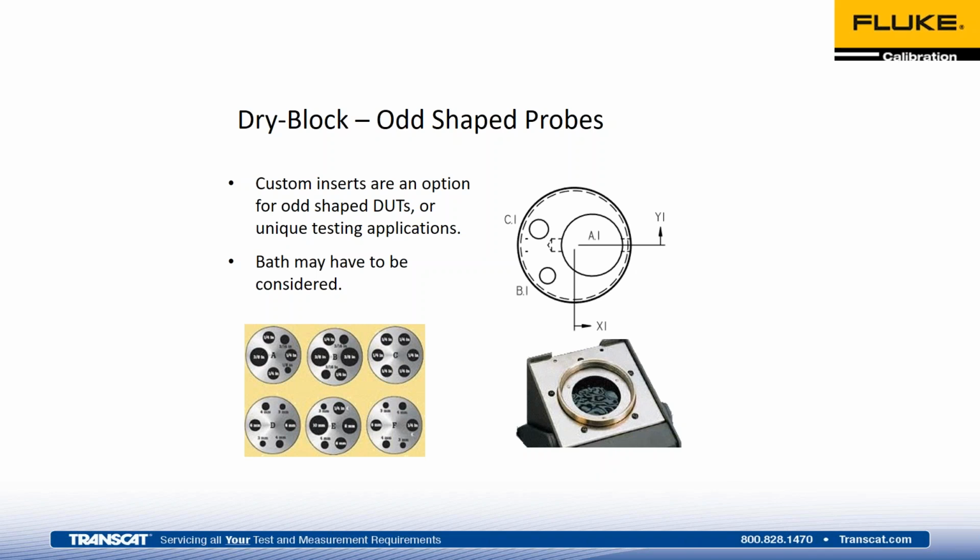Usually if the DUT is that extreme, most folks will consider a bath, but there are those times when a bath is not going to happen or it cannot be used. So there are workarounds. It does add a little bit of uncertainty when you go that route, but again, it can be worked around. Most dry wells, though, will come with some sort of a standard block design or insert. So down there on the left is kind of more common what you would see regarding typical size. Usually we've got our standard sizes and metric sizes to choose from.